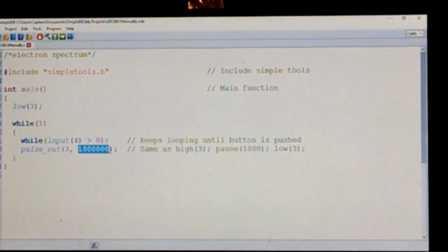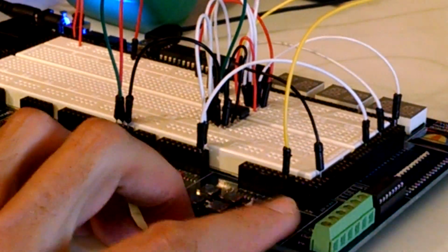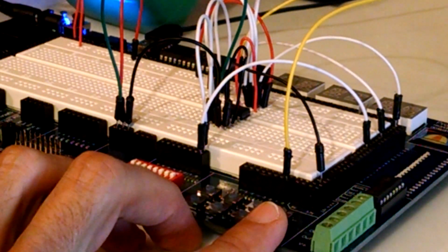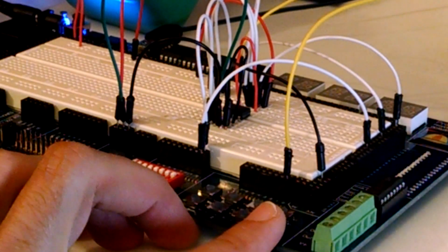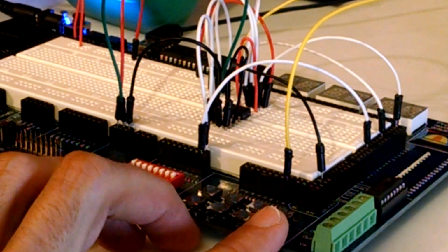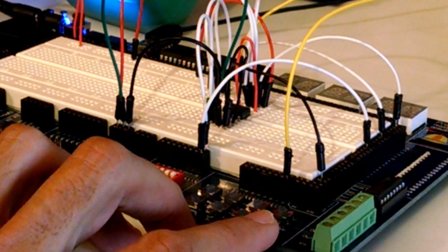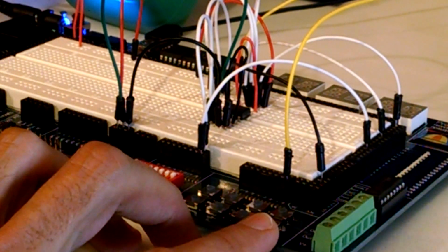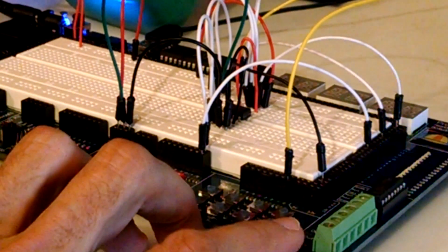In case you're wondering why the push button isn't connected directly into the ADC chip in this example, it's because one push with this kind of a push button is often represented as more than one clock pulse by these ADC chips because they work fast in the microsecond scale. So for the clock pulse, we will use the microcontroller, but still trigger manually.